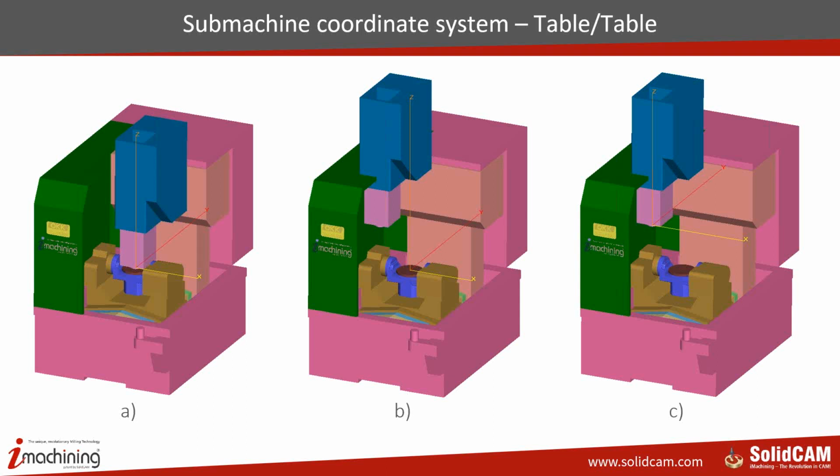In the past, we just moved the spindle to the table of the rotary axis and put the global coordinate system there. That was the rule in the past, but today SolidCAM implements very nice options, and there are no limits regarding where you should put your STLs and your coordinate system.